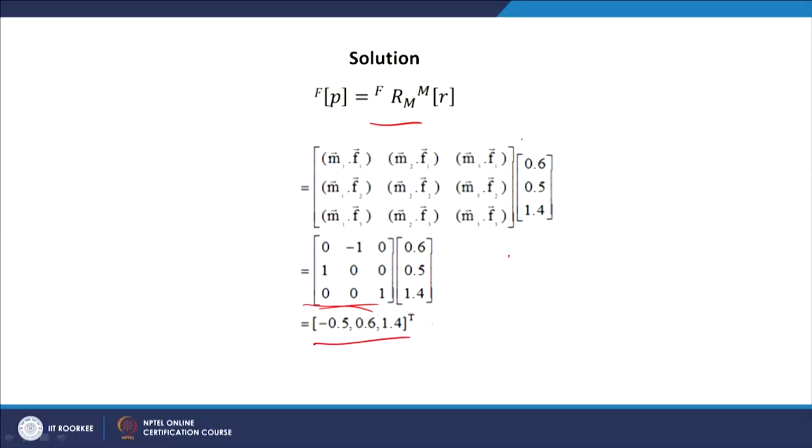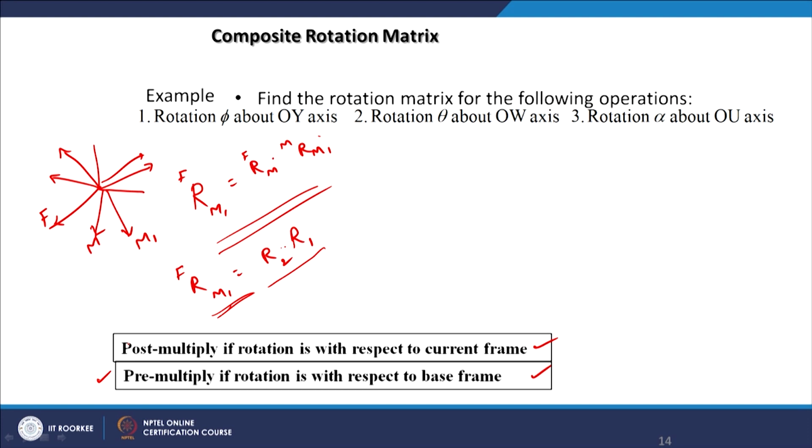Similarly, we can show that if we do the rotation every time with respect to the base frame, then we have to pre-multiply the rotation at every step. So, this concept will be very useful in understanding various coordinate frame related concepts in robotics. That we will see in the coming lectures.